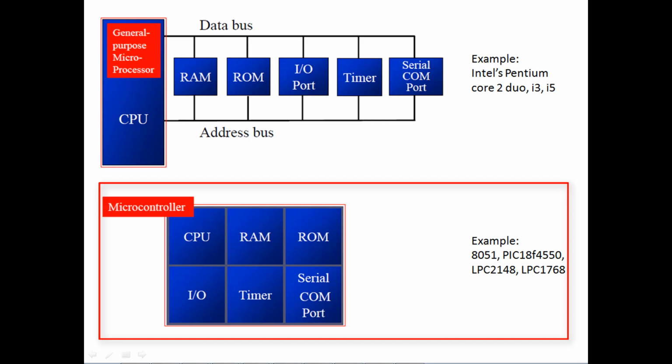Microcontrollers are designed to perform specific tasks. Depending on the input, some processing needs to be done and the output is delivered. For example, washing machine, digicam, pen drive, remote, microwave, etc. Since the applications are very specific, they need only small resources like RAM, ROM, and input output ports, and hence can be embedded on a single chip. This in turn reduces the size and the cost.